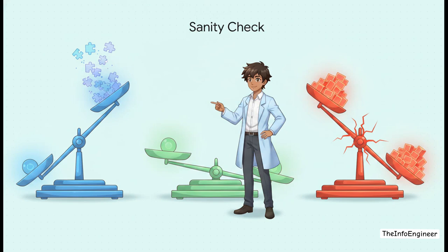Now, you might be super tempted to just start throwing algebra at the wall to see what sticks. But hold on. Before we do pages of calculations, we must perform a crucial sanity check, also known as a degree of freedom, or DOF analysis. You count your unknown variables, and then you subtract the number of independent equations you can write. Here is the golden rule.